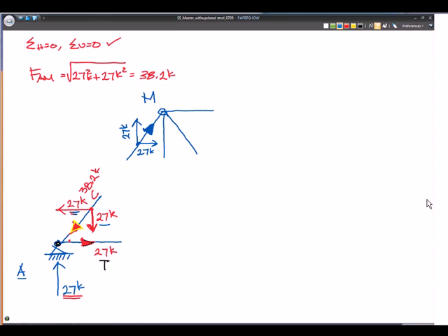So it's equal and opposite to the other end, and it's still signifying compression. It's pushing on the joint. Don't look at these members as a whole, because they look like they represent tension, like they're pulling away from each other. That's why you always remember it's called the method of joints. What is the force doing to the joint?